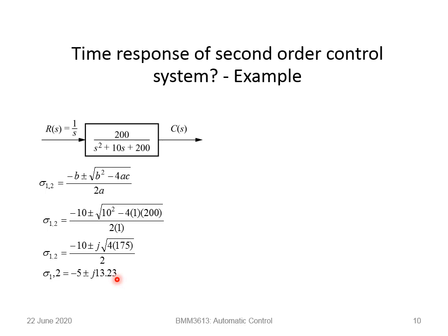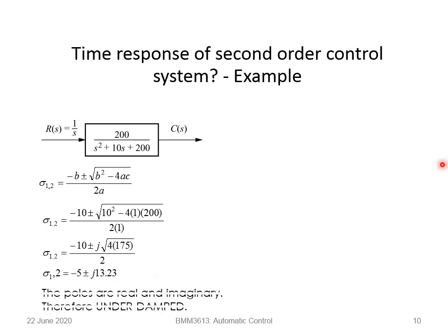So what type of response is this? Please look back at the lecture and find out what type of response it is. If you look at it, it is an underdamped system, right? It is a system that decays but still has undulation, so it is an underdamped system. An underdamped system has two poles, each with both a real and an imaginary component.